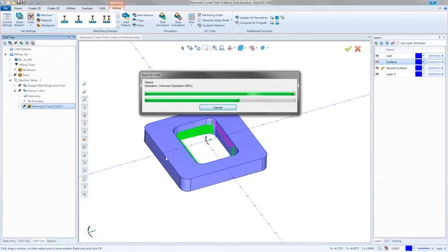But you still run into the fact that you're using a lollipop that, without that geometry being extended, might not offset properly. Even if you could get it to go past the bottom of the part, it might drop and consider that wall to turn kind of straight, which I guess wouldn't be the worst thing in the world if it went straight after it got past the bottom corner. But yeah, you shouldn't have a problem with that with the ball mill.